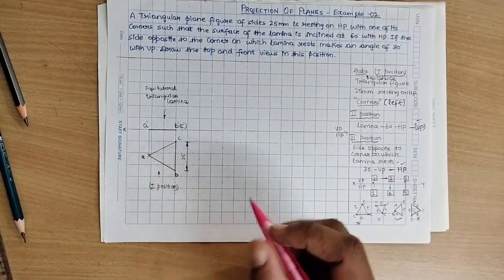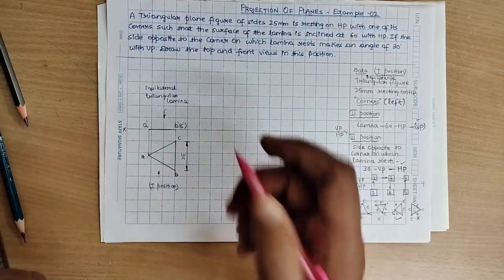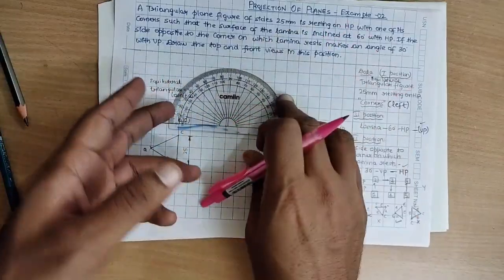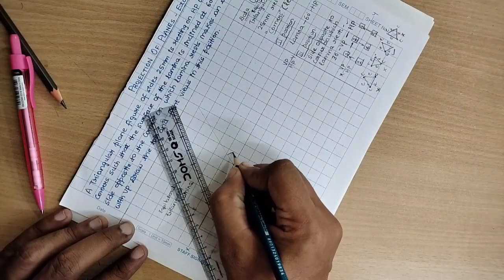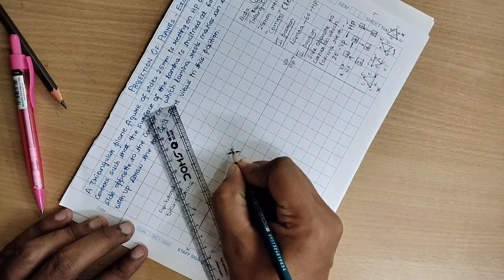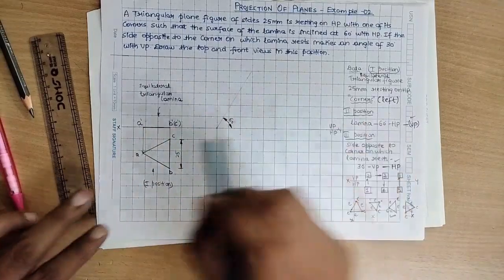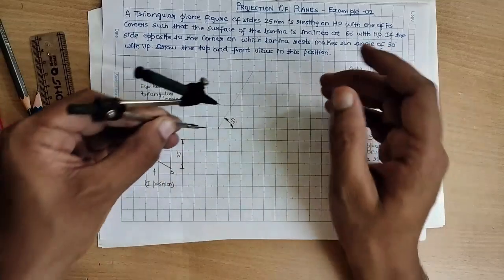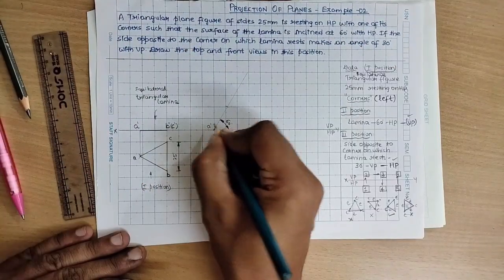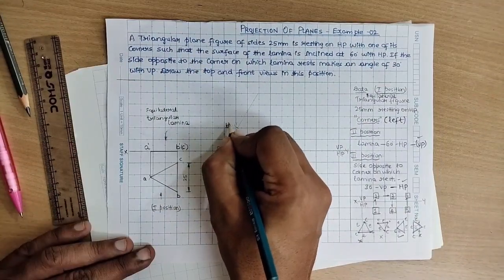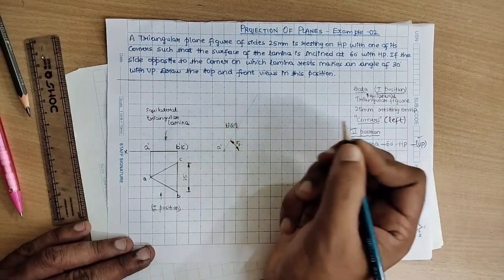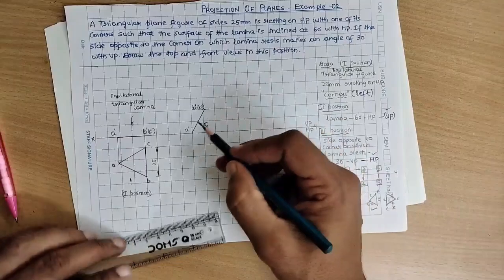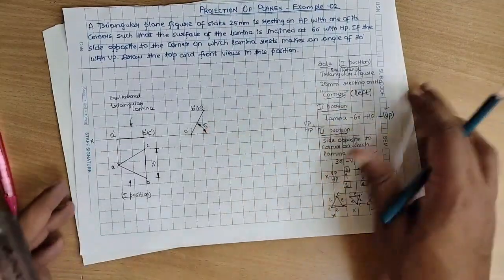Make use of your protractor. Take any convenient point. Mark any convenient point. Measure 60 degrees in the protractor. Call this angle as 60 degrees. We are having 2 points. Let us transfer the 2 points using compass. A as the center, AB as the distance. This is the point A dash. This would be the point B dash, within the brackets C dash. Extra projections are there, we can remove them. Since this is a part of the object, we can darken this one.